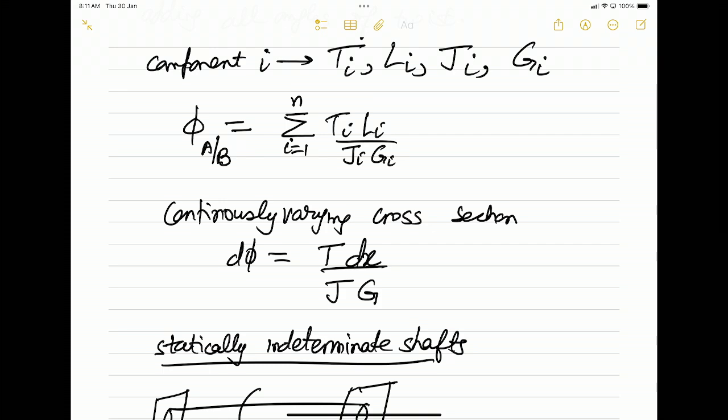It is something like I ZZ, because I ZZ is the integral of x squared plus y squared dA. So this J is what you have seen in your course as I ZZ, but without the mass, only the geometrical part. The density has been removed. And we showed that for a circular shaft it is pi by 2 times the radius to the power 4. Okay.